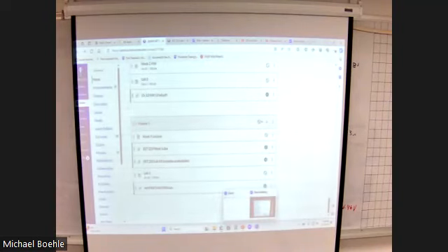When we do that, you can find the determinant of the matrix. The initial matrix is going to be the coefficients for current 1, current 2, current 3. That's your input. Then you take the constants and substitute them into each unknown that you want to solve, the I1 column, the I2 column, the I3 column, solve that determinant, and then take the value of those determinants, divide them, and that's your answer.